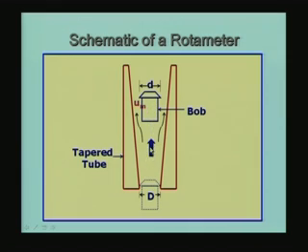these 3 forces are going to now be in balance for a particular value of the flow rate. We will see later that um is going to be a constant value, because the drag force, the weight of the bob and the force due to buoyancy must always be in balance, okay. And this will be for a given value of um. The um gets fixed because of that, and what is changing here is only the area available for flow, that is the annular area surrounding the bob.